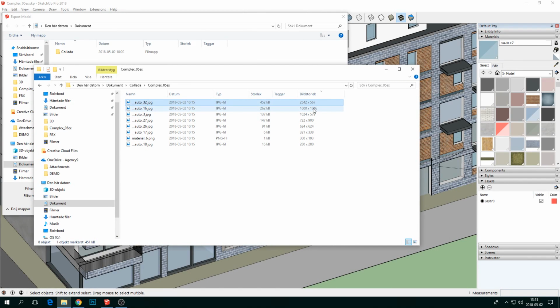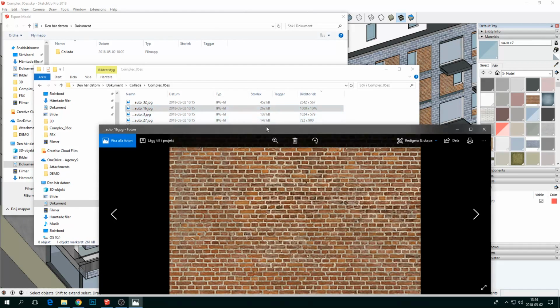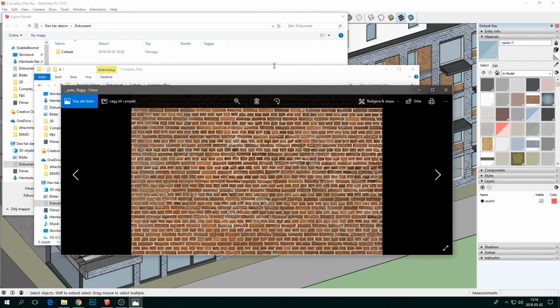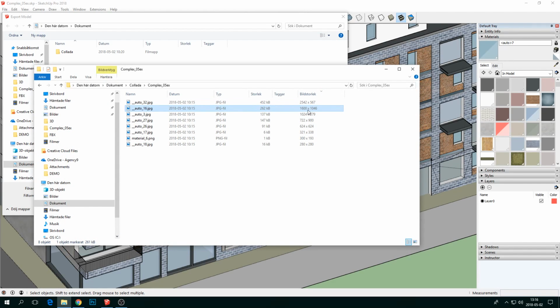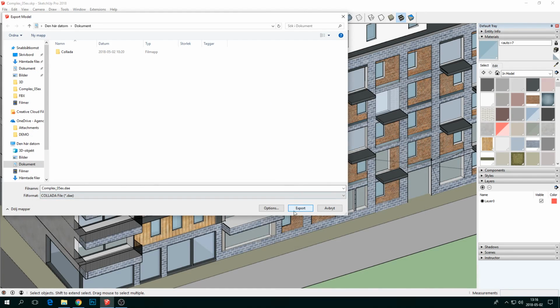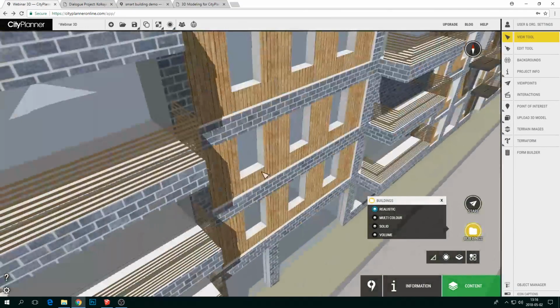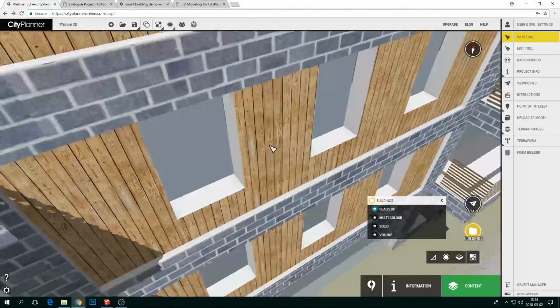So as you can see here, the resolution of that grass texture or this brick texture is way over 1,000 pixels. So what do we recommend? Well, as always, it depends on what you're trying to communicate, but a general rule of thumb is no larger than 1024 by 1024 pixels. Because in a general sense, in general visualization, people don't really zoom that close into a brick wall and study the exact texture of the thing. So exactly. And here those textures are actually not too big, and they look good in the scene.